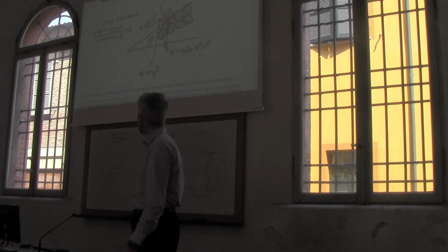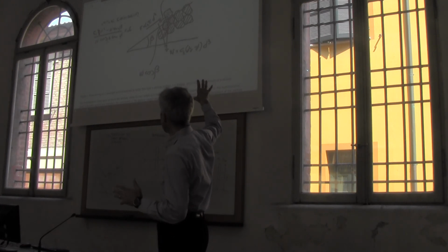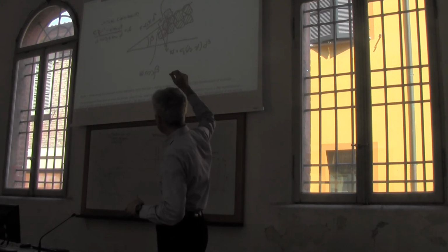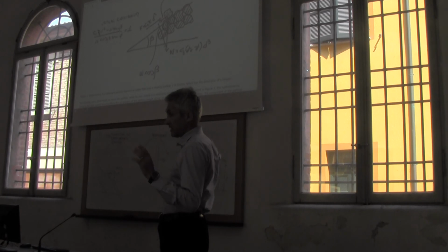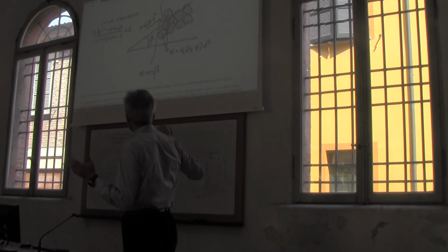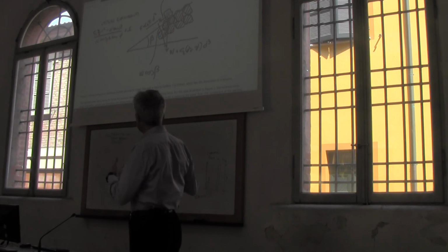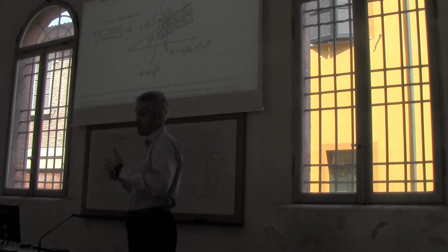So let's make reference to this sketch. In this sketch you see that you have an ideal structure of a groin with an armor unit on the side that is located there, and let's study the stability of that armor unit. Keep in mind that the shape here is, for simplicity, depicted like a rectangular shape, but the shape may be whatever.